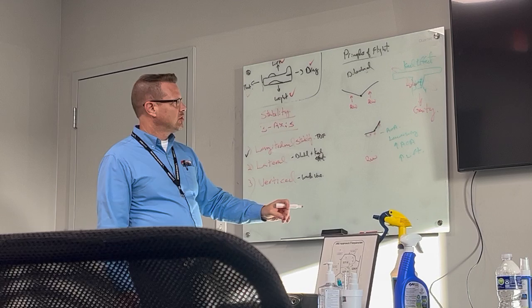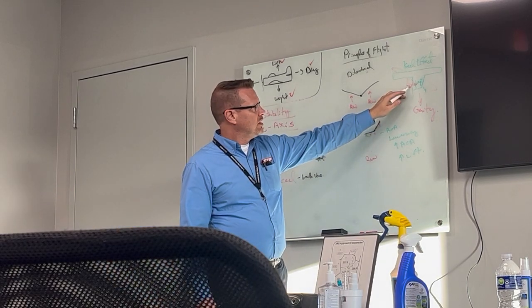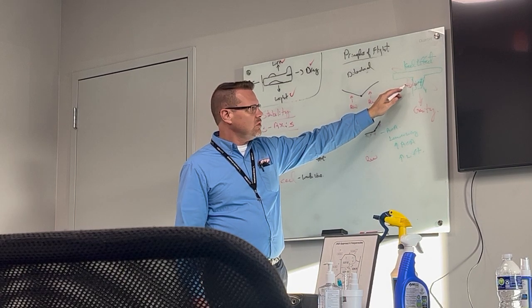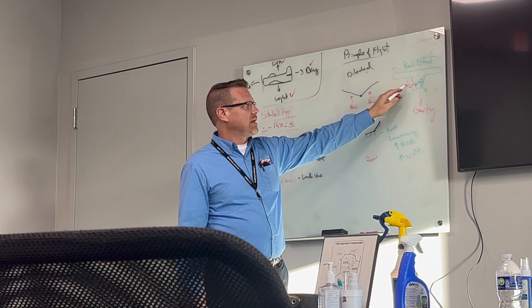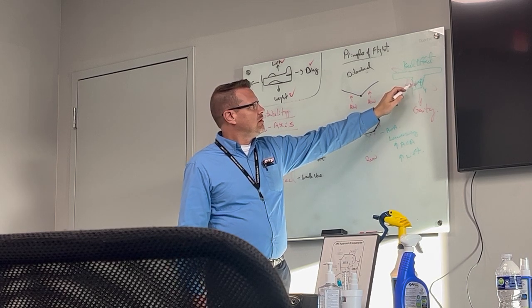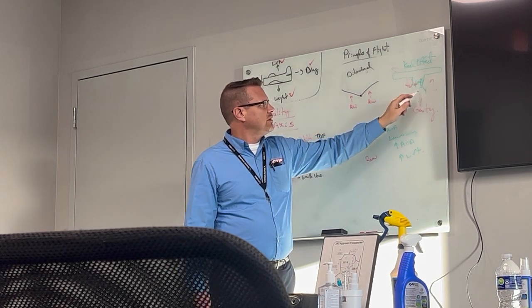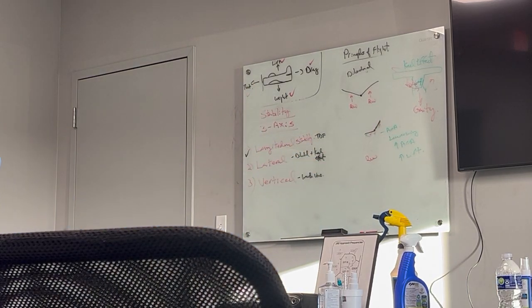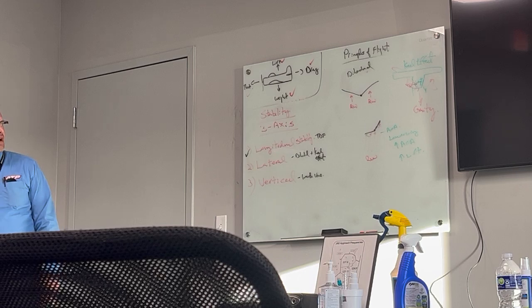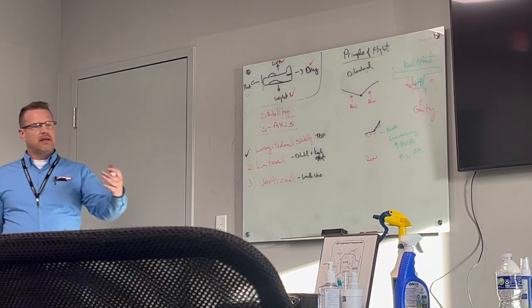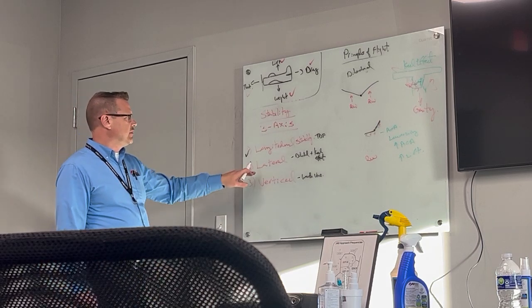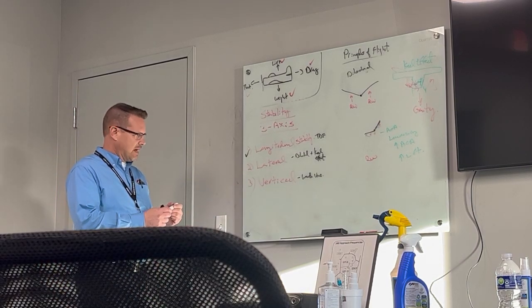You know, it's basically you're taking that force and you're taking weight, or the center of that weight, and you're moving it out from underneath the center. Well, gravity's not going to like that. So if it's undisturbed, we have that dihedral acting. We also have the weight itself wanting to shift back to be in center and equilibrium, right? Caused by gravity. So it's the dihedral and the keel effect combined that gives us our lateral stability.